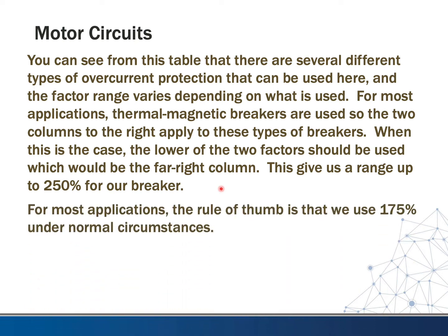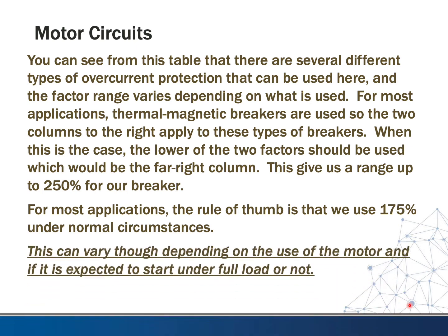For most applications, though, the rule of thumb is that we use around 175% under normal circumstances. So breakers that would be feeding mechanical equipment or some other equipment like that, if we're using the inverse time breakers, which we almost always are, then we usually size those to 175% under normal circumstances. But that's not always the case. This can vary, though, depending on the use of the motor and if it's expected to start under full load. If it is, then we would upsize this breaker size, like for an elevator or something like that. We might use something larger.